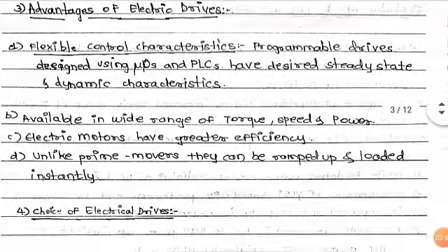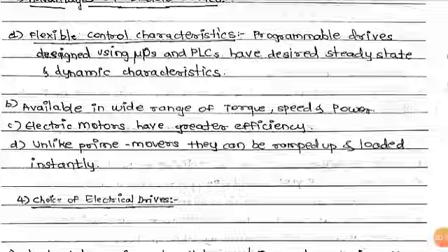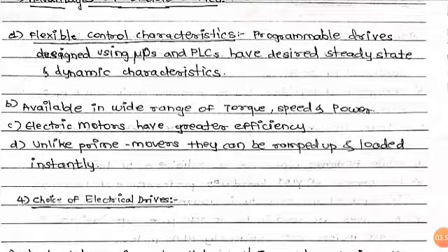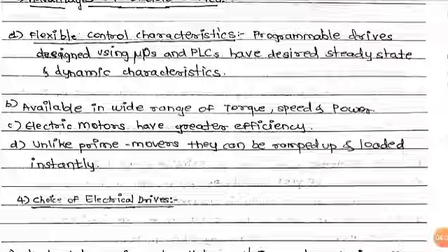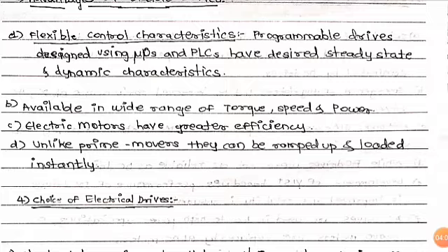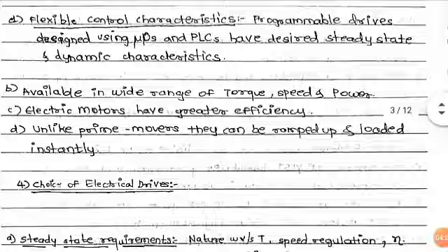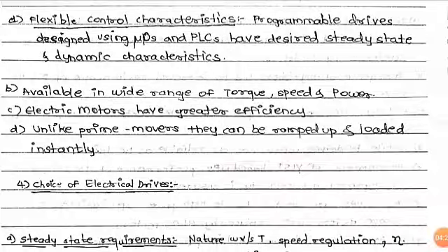In that case, for some time the torque goes negative, and then the speed reduces from 1000 to 800, and then again the torque becomes positive and remains constant. So during this change from 1000 rpm to 800 rpm, the speed and torque both were changing. Therefore it is called dynamic operation. So steady state as well as dynamic characteristics, we can achieve any desired operating point.